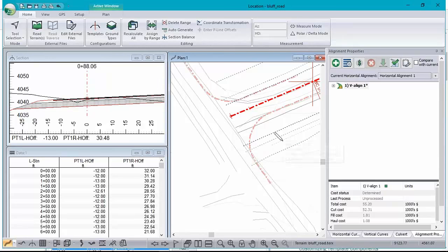So in the location module, there is a way to attach points from your template to a thing called a reference feature, so we could do this all automatically. Currently, the alignments in the background here are not reference features. So if I wanted to use the reference feature method, I'd have to get those into my terrain. I can do that, and that would be another step in this process. But instead, I'm just going to do it manually, and it's not that hard.